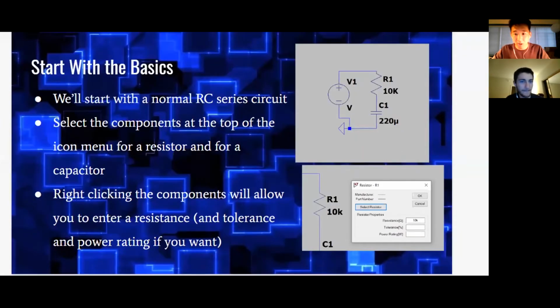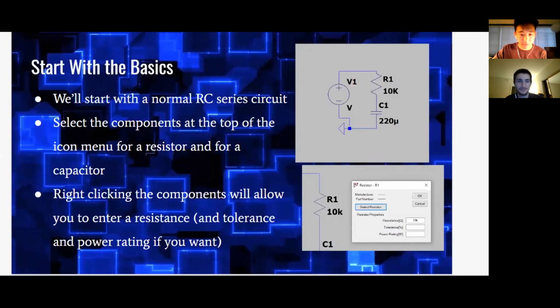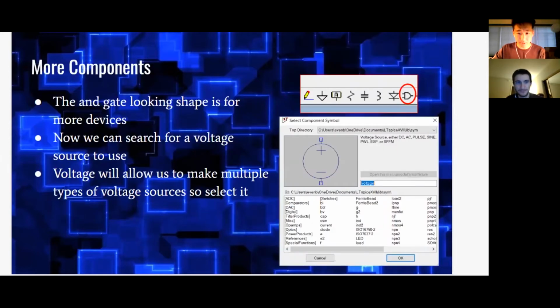We've gone through a lot of these steps already, but just to make sure we didn't miss any details, we've put them here. So we put on the components, and then we put on the specific units, and that gate object in the toolbar allows you to access a lot of different library components. You can go online and download a bunch of LTSpice compatible components, and have them modeled into your circuit. That's really useful.